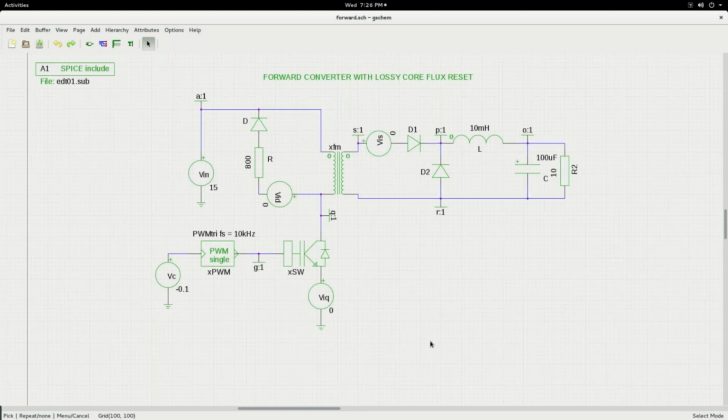So now you see I have made the changes which I said I would do, which is to put a source here, a source here, and a source here. Observe also that I have put zero voltage value at all these sources, so these are now behaving like current sensors. I have put the positive terminal in such a way that the current flows into the positive.